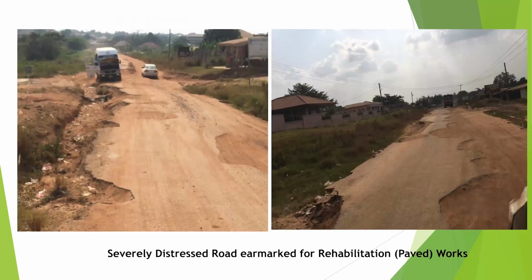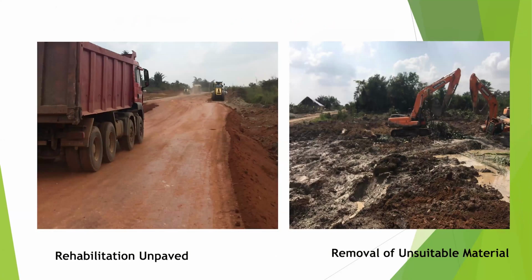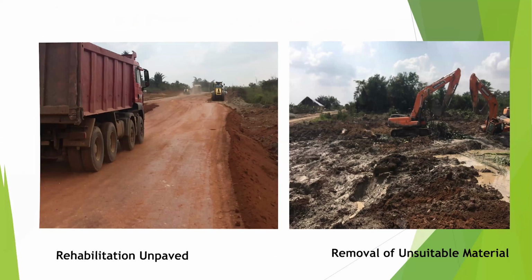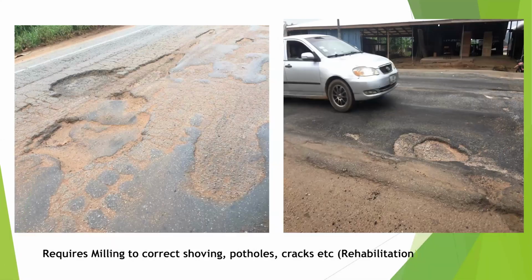Now, these are some pictures that we have. And this is a very clear, typical, and highly deteriorated surface. This one, you have to do rehabilitation completely. Then you also have some regraveling, some swamp treatment on suitable material that you would also have to undertake on some of our roads. When you have drainage issues, when you are packaging a project, you need to consider the drainage aspect and also treat the accesses. And so you have some of these things coming into play. Although it's a resealing project or overlay, you need to cover those activities.